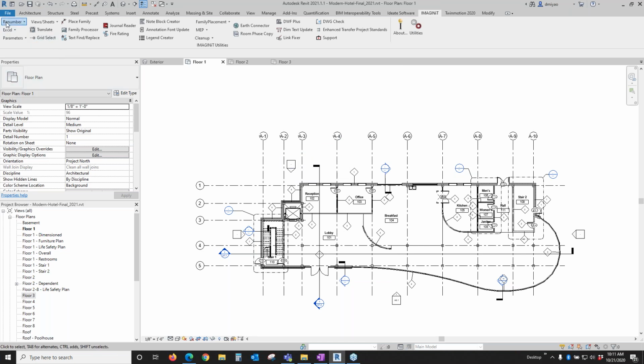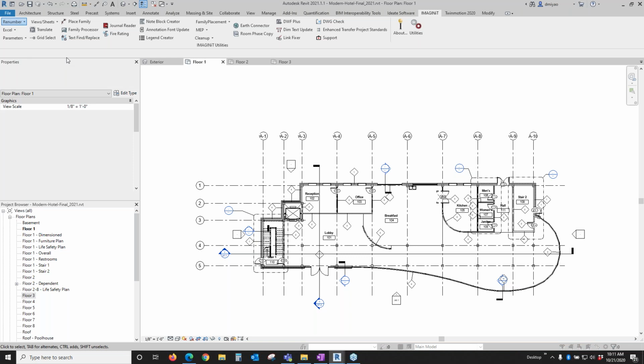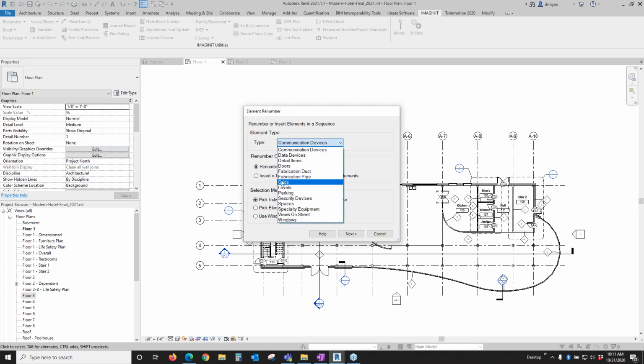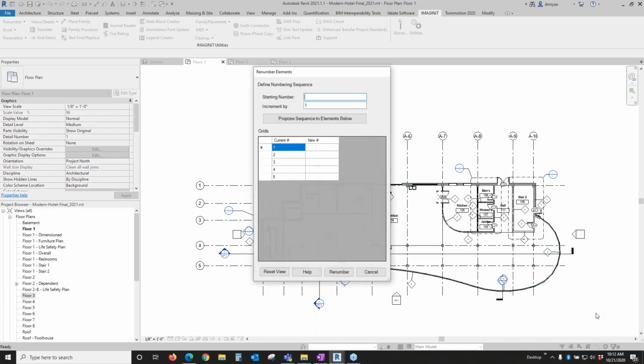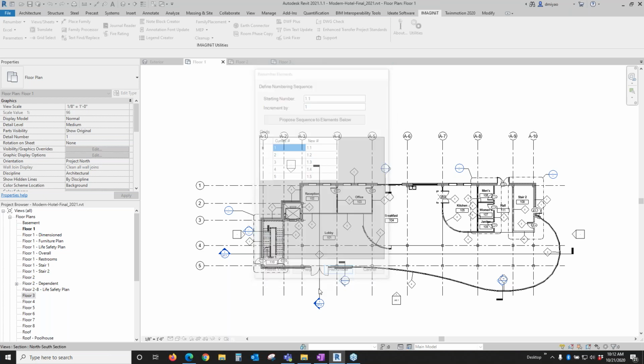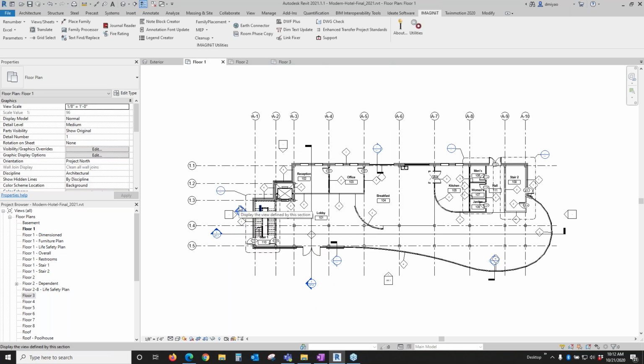So we go back to renumber my elements. And again, I want to select my grids. Again, I want to use my select by window, next, put a window around those grids, hit my escape key. And again, I want these to be 1.1, and then I want to click on my proposed. There's my proposed grid numbers, say OK. So there you go. So I can, again, very quickly resequence, renumber a variety of items inside of my Revit model.